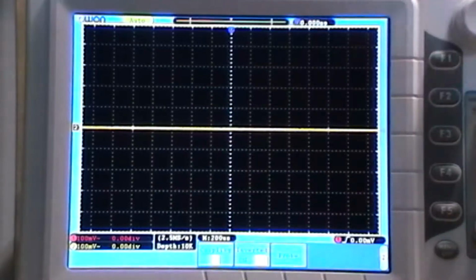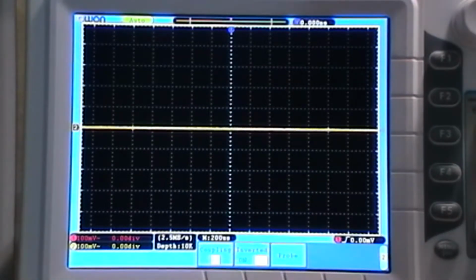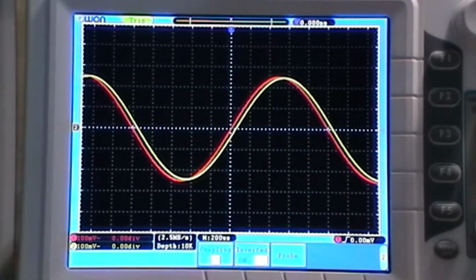Getting the 47 nanofarad. So supposedly I should have a higher frequency because now I've got a lower capacitance. So still half a volt, still 500 hertz. Turn that on, and obviously we're getting pretty much most of that signal through. I've actually calculated it being 3.38 kilohertz or 3.4.